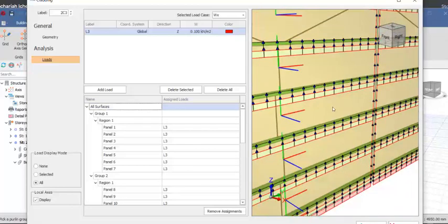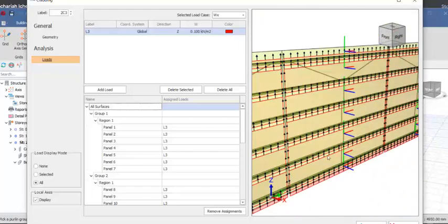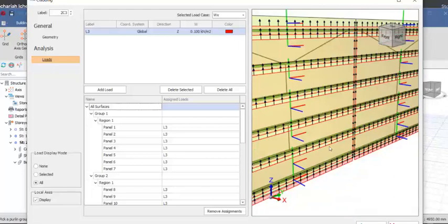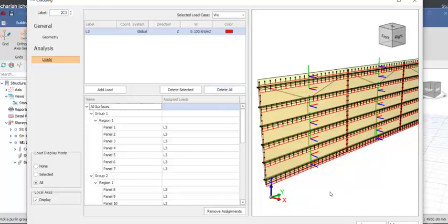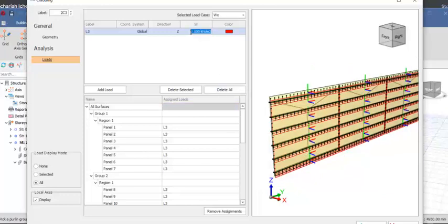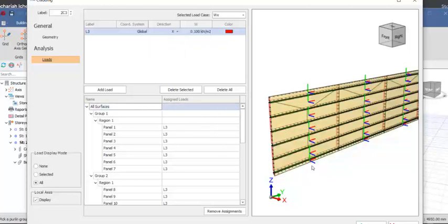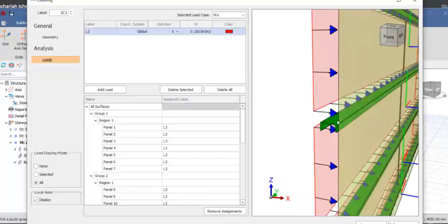It is acting from the lower side upward, but it's supposed to act perpendicularly. That is why most of the time we don't normally use it here, or use it over where we key in the basic wind speed. But in the higher versions of Prokon Structure, you can actually incline this load to horizontal directions. So you can now change direction here as well. See the direction provision. You can change it to X. Once you change it to X and then apply that, you see now it's being applied in that opposite X direction.